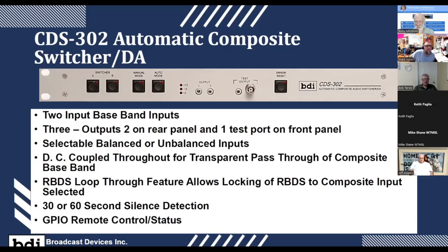And all of those things are important for good FM stereo performance, for separation and for modulation density. You don't want anything to add to your modulation component, like overshoot or anything like that, that can rob you of modulation. So if you're still doing baseband, you'd be surprised. Again, I know a lot of new transmitters are out there that have all of this stuff built into the exciter, but there are still a lot of people out there that are still running older transmitters.